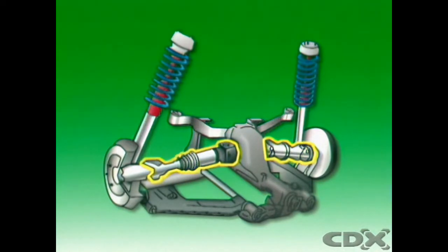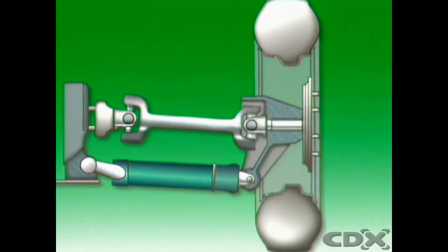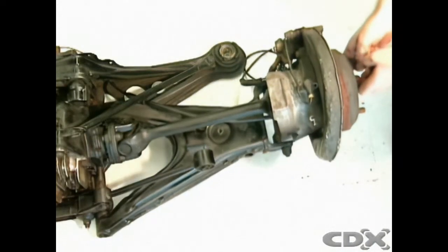Drive shafts, either with conventional or constant velocity joints, transmit the drive to the wheels. When conventional universal joints are used, each drive shaft may have a splined section to accommodate changes in shaft length due to changes in wheel camber with suspension action. However, the drive shaft itself can be used as the upper link of the suspension, providing the pivot point. The spline section is unnecessary, and the shaft can be made as one piece.